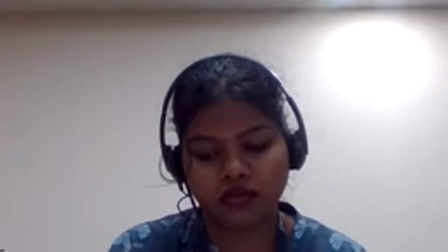You've got the data, right? The data is saying you need a 6 log reduction. The D value at 121 degrees centigrade is 3 minutes. What will be the F0 value for that? Sir, is that 18 minutes? Yes, it is 18 minutes. Who answered that question? Priya. Yeah, that's correct. Why, Omkar, are you having a problem getting that answer?